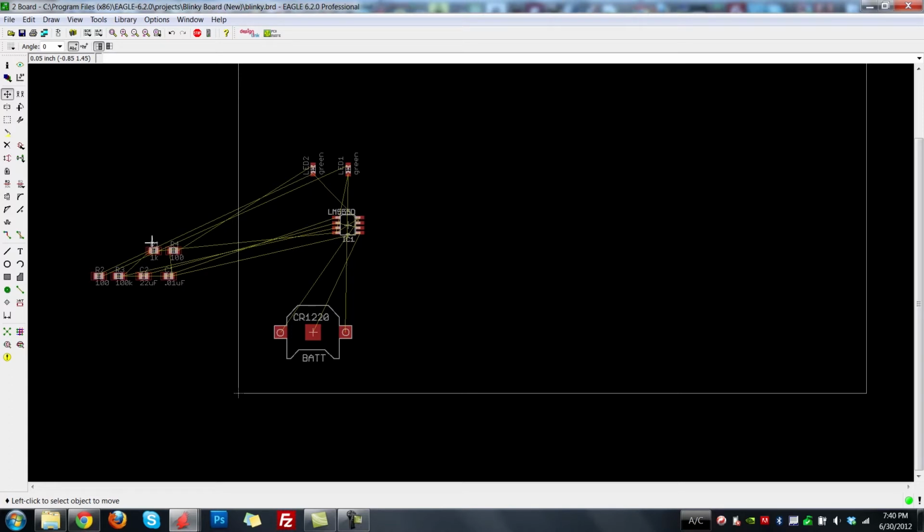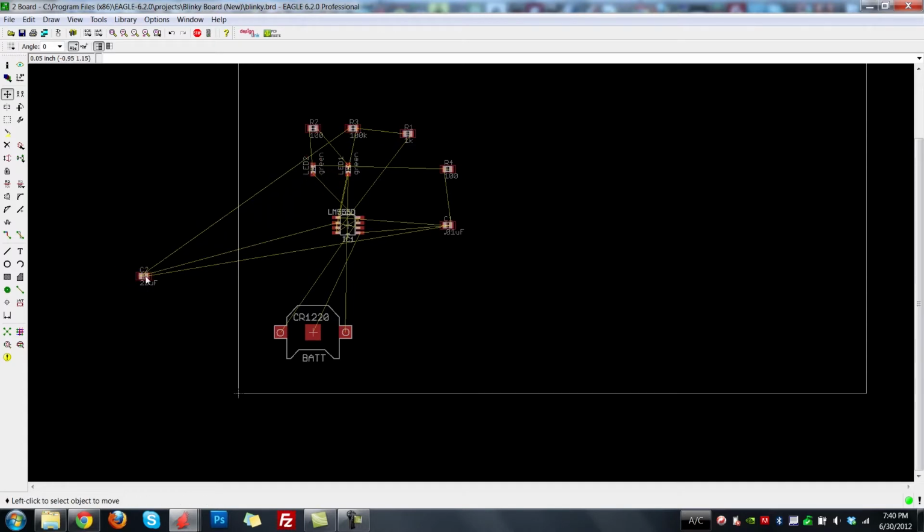Often some of those inner layers will be ground or power planes that are used to route various voltages or to connect the grounds around the board. This is common on things like computer motherboards, where you'll find extremely high numbers of layers and high density component packing. If you recall from the first video, we chose 0805 resistors and capacitors, which is what's determining their size here in the package that we're using.